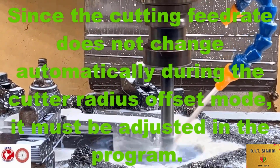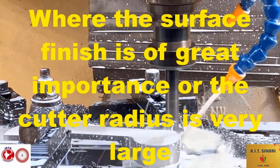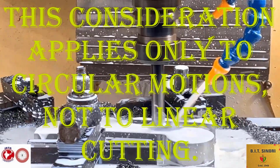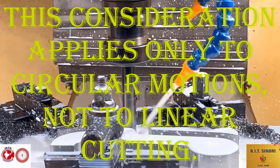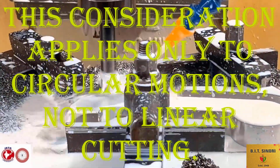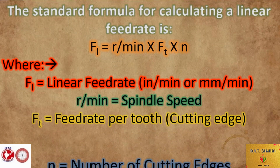Usually, this adjustment is not necessary except in cases where the surface finish is of great importance or the cutter radius is very large. These considerations apply only in circular motion, not to linear cutting. In normal programming, the linear feed rate is used for arcs as well, as determined by the machinability rating for the given material. So first, here is the standard formula for calculating a linear feed rate.